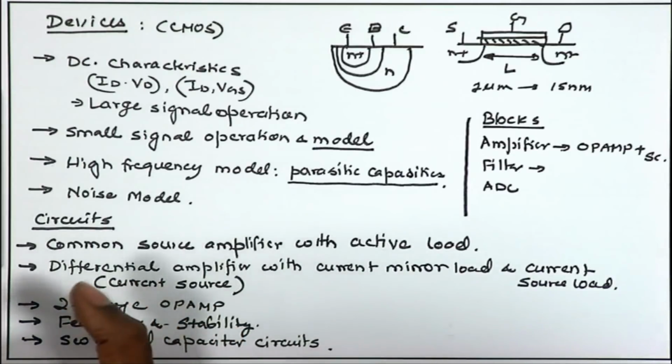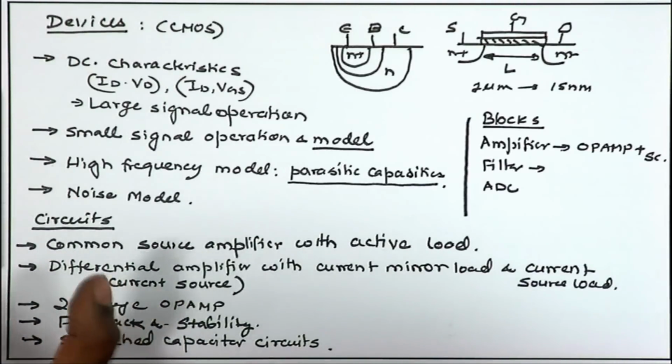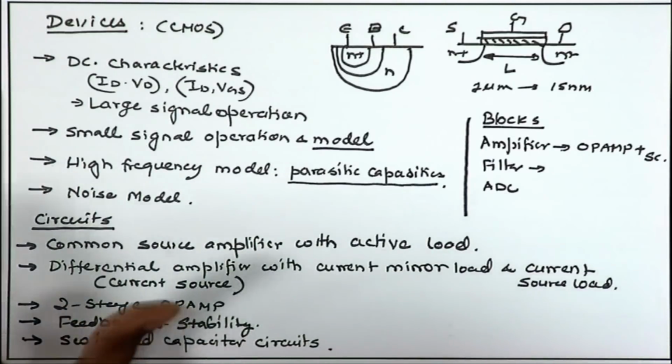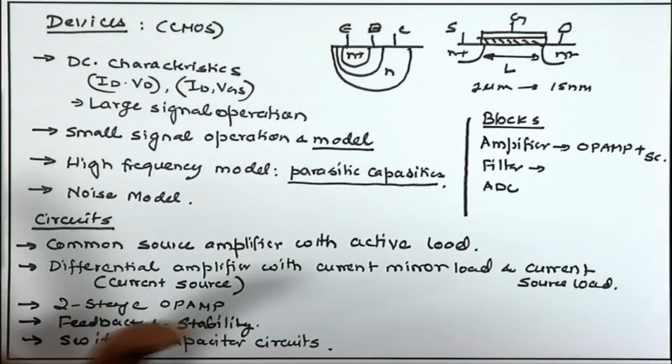A single millimeter square area chip cannot afford more than say a nanofarad of capacitance. So, total capacitance summed together in the entire 1 millimeter die can be limited to 1 nanofarad, and in general individual capacitances used in the circuits, for example in 180 nanometer technology, may be well within 100 picofarad. There will be very few around that range, most of them will be a few picofarad or smaller.